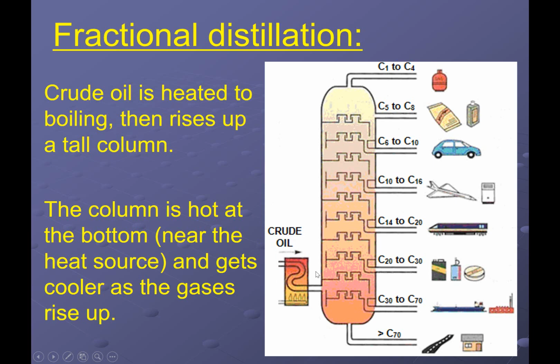The first thing I want to emphasize here is all of it gets heated. We try to vaporize all of them. Some of them came in as gases, some of them came in as liquids at first, but we're heating it up. In a textbook, we will see about 400, 500 degrees or so. That's usually hot enough to overcome those London forces, those dispersion forces. It's enough to make all of them gases that transfer through the rest of the column.